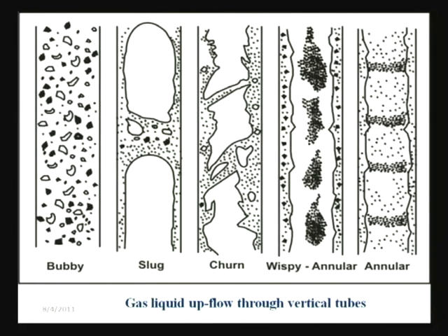Okay. And what happens is, from the preceding liquid slug, the liquid starts flowing downward as a continuous liquid film along the surface of the bubble, and it forms an annular continuous wetting film between the tube wall and the bubble surface. Then it comes down and finally meets the liquid slug beneath.